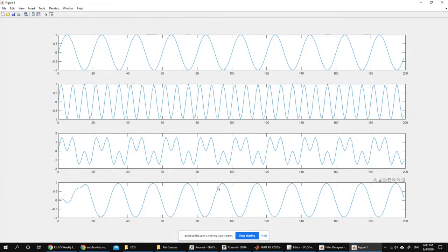But if you look at this, the signal actually looks okay. But sometimes, when the signal with the artifact is a little bit larger than the actual signal, for example if you have EMG, then you will have a problem with this, because 0.1 of a signal that is 10 times the true signal would make a problem.